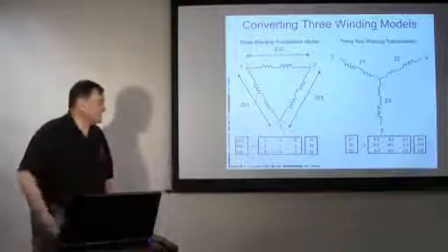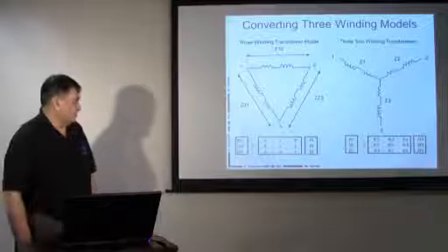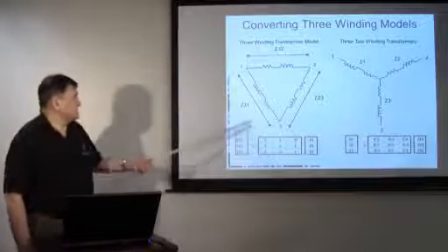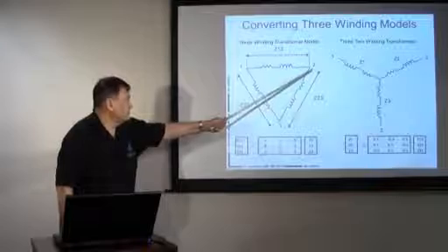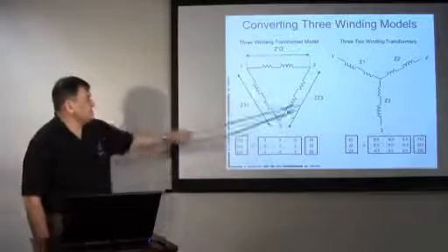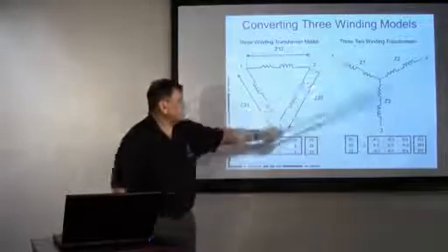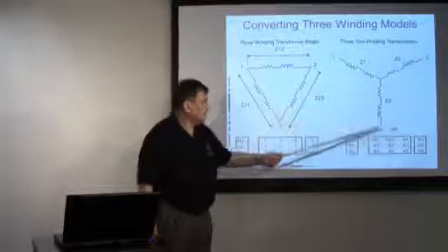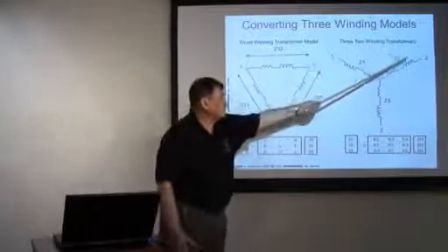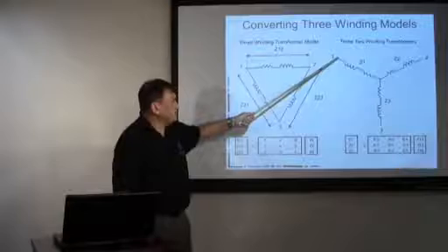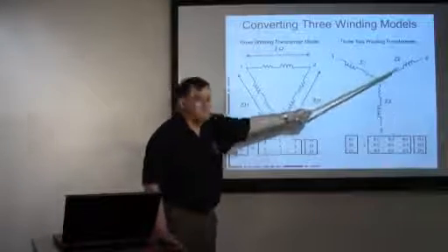So there's a process you have to go through here where we can say that the impedance across terminals 1 and 2 has to be the same as this impedance plus this impedance, doesn't it? This one is open. So if we impose a voltage source across here, the amount of current is going to be determined by Z1 plus Z2.